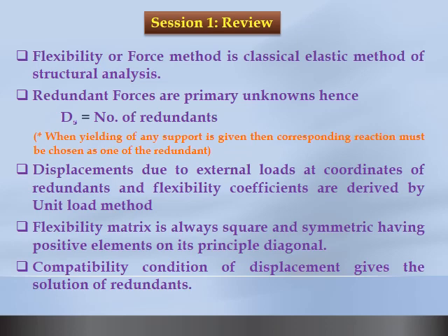First, the flexibility or force method is a classical elastic method of structural analysis, and as we are adopting matrices, it is called the matrix approach. The second point is that redundant forces are our primary unknowns. So to get the redundant forces, we want to find the degree of static indeterminacy.